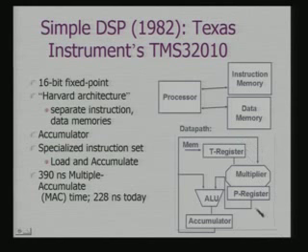Now if you look in here, you have an accumulator, a classical accumulator which participates in these arithmetic operations, and a specialized instruction containing load and accumulate. So here let us look at these internal organizations and look at the data path. What you will find here is that you have a dedicated multiplier, because multiply has to be operated at each step in the FIR filter, and it is to be used with the entire sequence of the data.